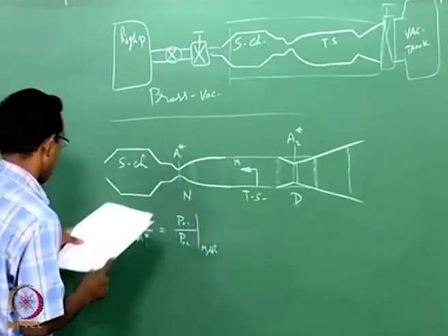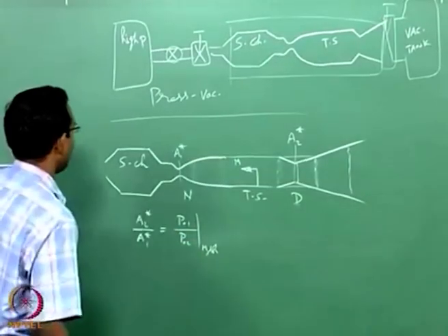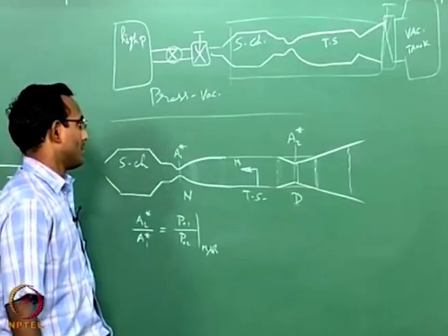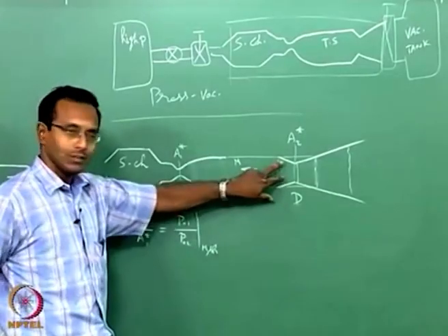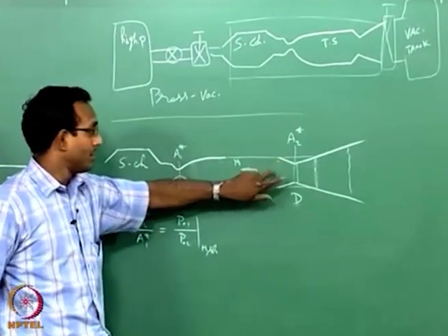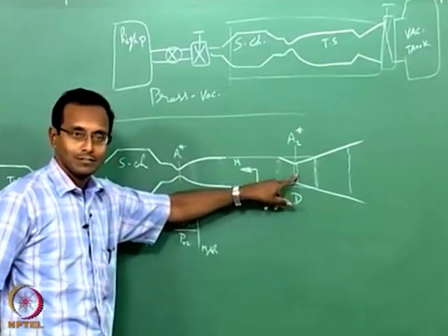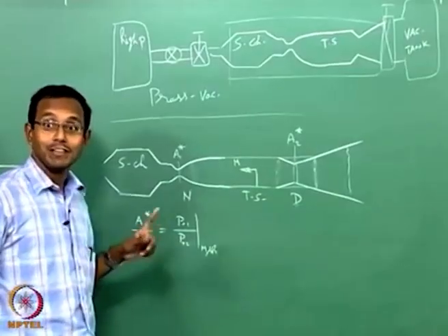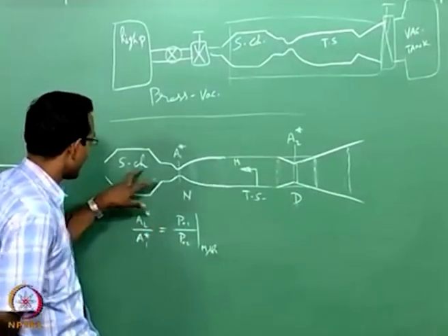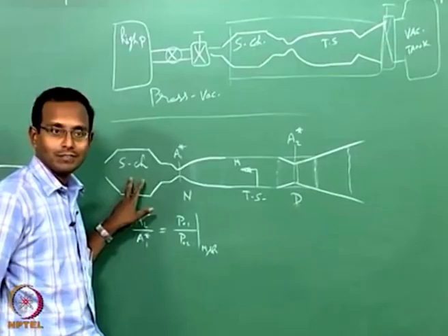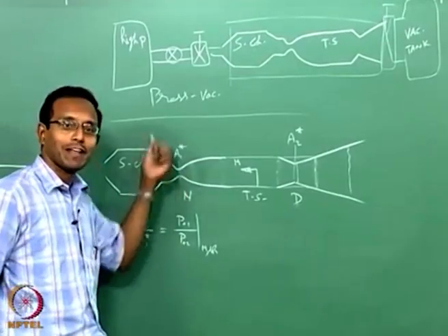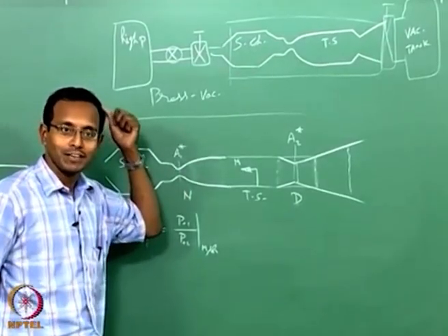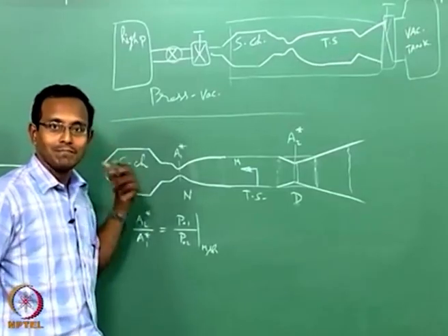So now if I think about delta T of running, if I have a second throat, then my P naught will be lesser. If I bring my shock to this point, P naught will be lesser and my runtime increases. Why? My mass flow rate is decided by the P naught. If my mass flow rate is less, I am not evacuating all the molecules from my original high pressure tank, so I will get runtime a little longer.